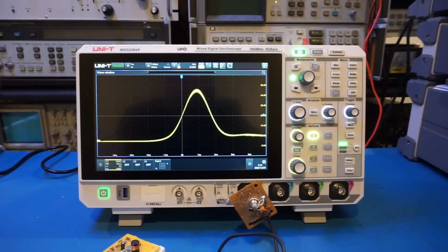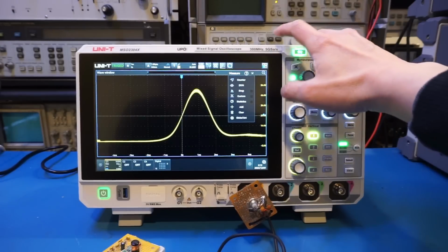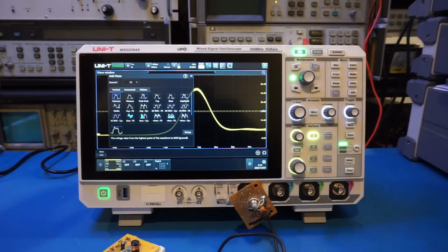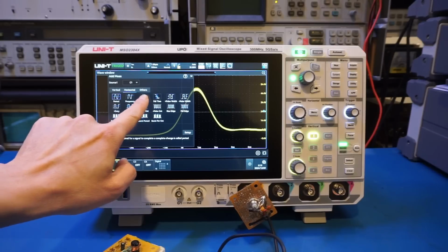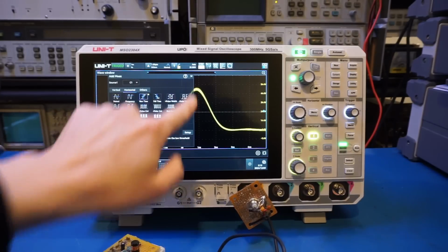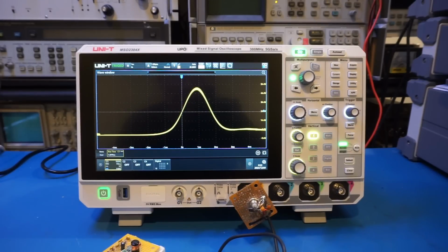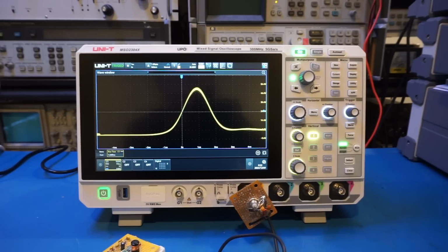And let's see what the rise time is. So I'm going to choose the automatic measurement. And let's do add. I think it's going to be horizontal. And here we go, rise time. So let's hit OK. The captured avalanche pulse is very, very clean. If you look at the automatically calculated rise time here, it's right around 1.25, 1.26 nanoseconds. This actually put it just slightly under 300 MHz.